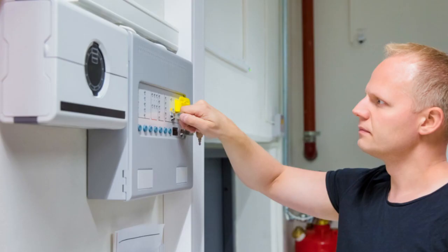6 monthly servicing and preventative maintenance should be carried out by a competent person with specialist knowledge of fire warning and automatic detection systems. This task is normally fulfilled by entering into a service contract with a specialist fire alarm company. The system should have a backup power supply capable of operating the system for a minimum period of 24 hours and sounding the alarm signal in all areas for 30 minutes.